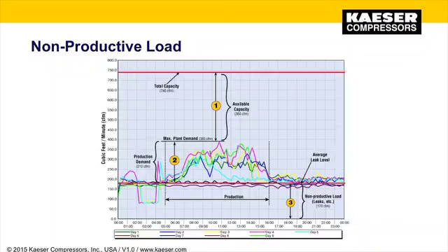A good audit will also provide you clues to non-productive loads, leaks, timed electric traps, etc. Non-productive loads can waste energy 24/7 as long as the compressors are on. In this case, the customer noted that a lot of air was being consumed after hours and on the weekends, when they were not in production.